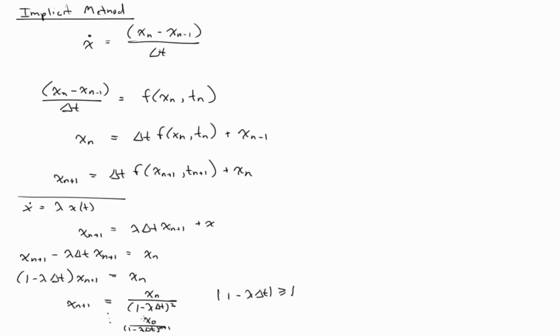Particularly in impact problems, where you have a lot of compression, right? And so you have this characteristic element length. You start with the elements this size, and then you're slamming it, you're compressing it, and at some point it becomes smaller than the characteristic element length because it's shortening, which causes your time step criterion to be violated, and then your simulation will go unstable. So in a second, we'll talk about a way where we can hopefully identify that.